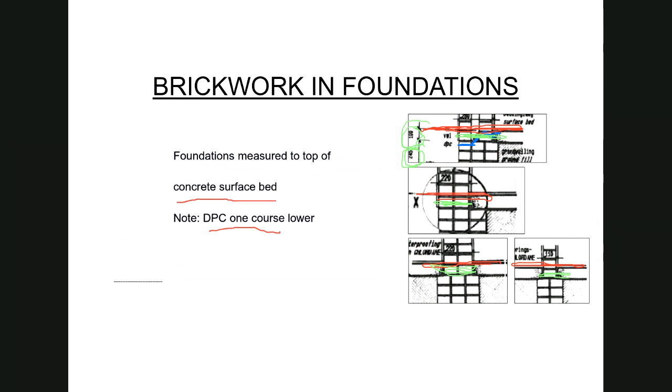So we're going to have a thicker foundation wall up to the 245 level, and then we are going to have a different thickness of wall on the 100 millimeter level over there. Okay, and you must bear this in mind as we go along. I will be very explicit about these 100 millimeter high pieces of brickwork.